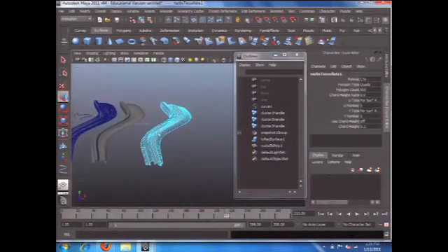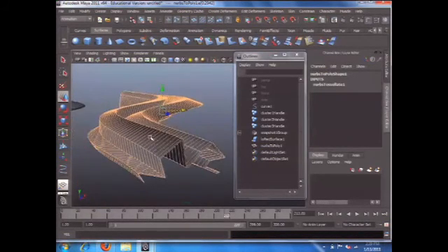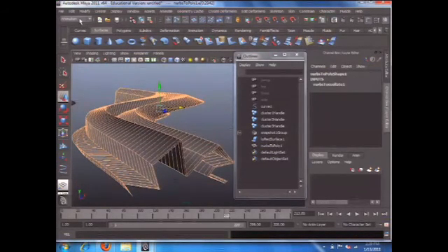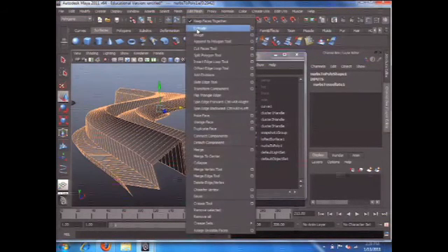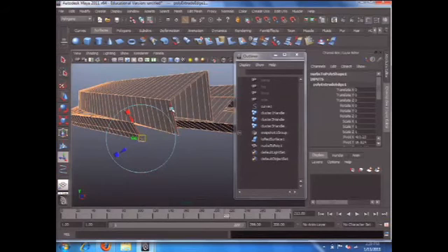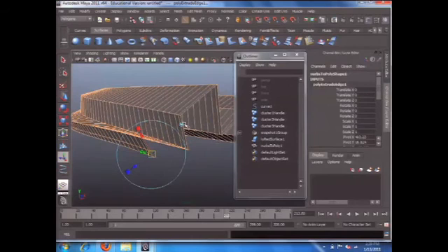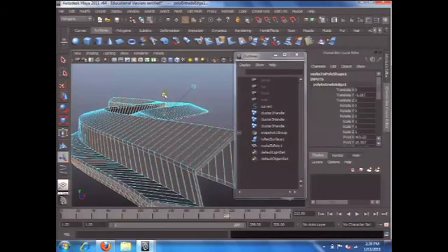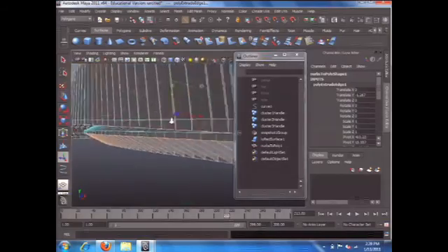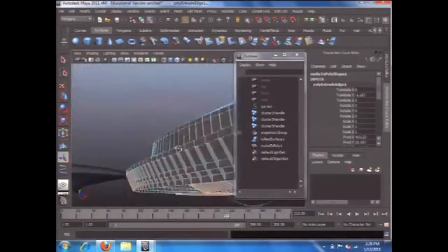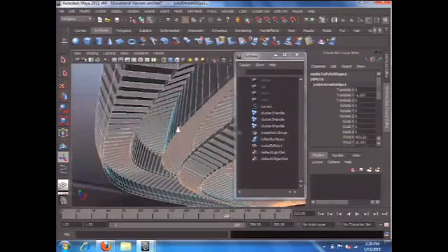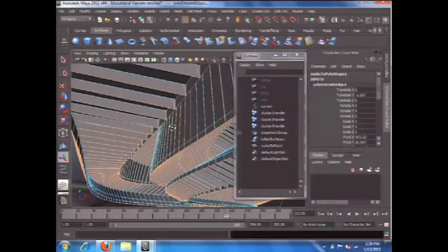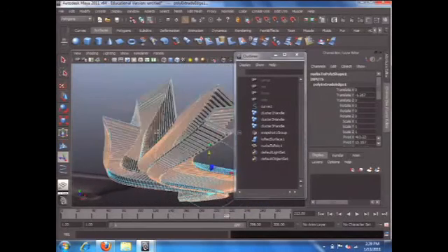I will select all the edges. And I'm going to extrude the edges. I will click this circle to change the coordinates from local to world. Okay. Then I will move. I can move up and down. I think moving down will make more sense. So move down a little bit. You can see this interesting internal structure show up, right? Like a frame system.